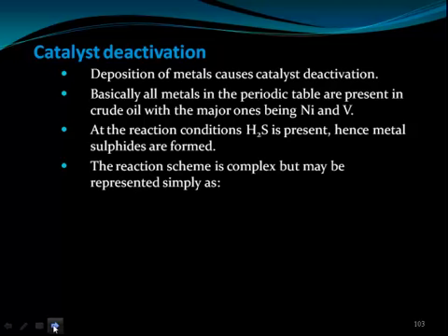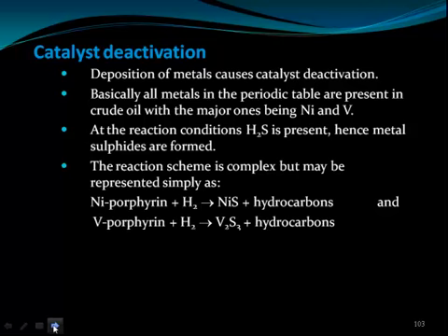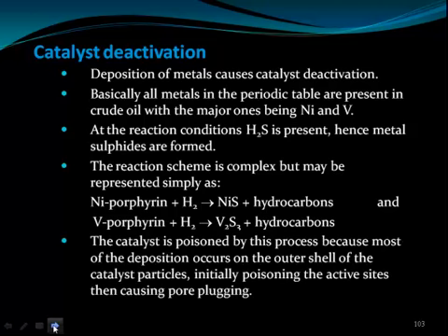So the reaction scheme is complex but may be represented simply as nickel porphyrin plus hydrogen gives nickel sulfide and hydrocarbons, and vanadium porphyrin plus hydrogen gives vanadium sulfide plus hydrocarbons. The catalyst is poisoned by this process because most of the deposition occurs on the outer shell of the catalyst particle, initially poisoning the active site, then causing pore plugging.